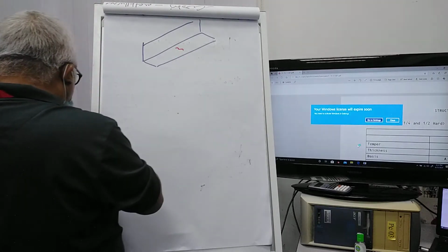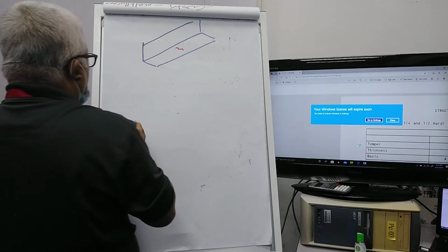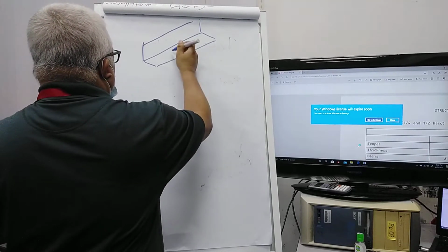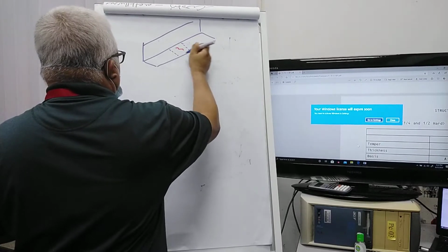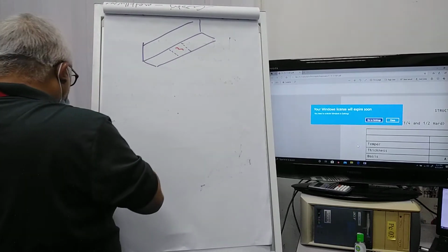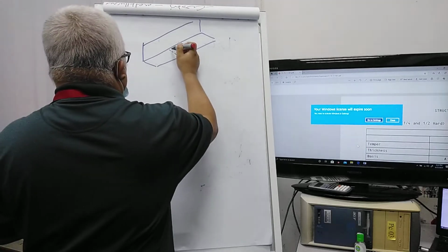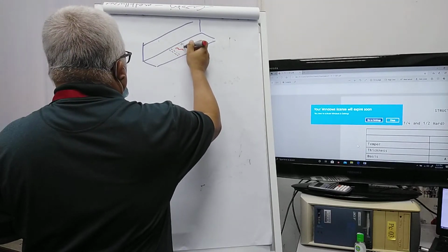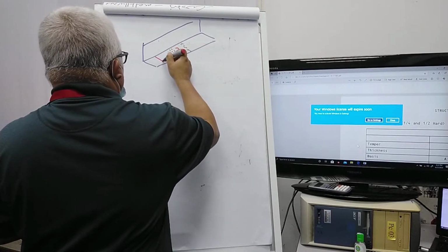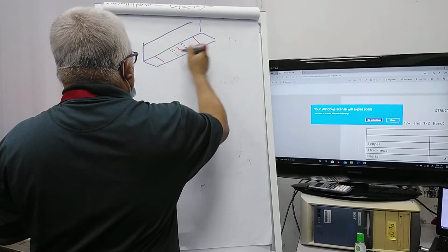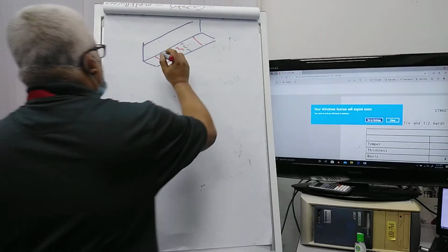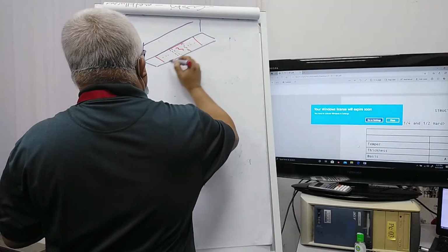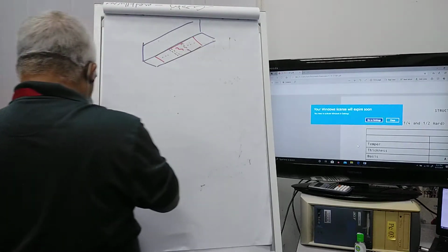We have a crack, so we cut this area off, and then we install a filler, and then we have a double plate. We have 3 rivets, so this plate is a doubler.